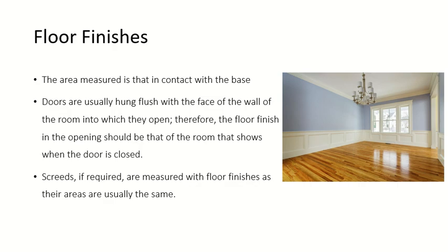I'm not talking about the area of the door. I'm talking about the area which is under the door when you open it. So there is no deduction done for that, because the door usually opens completely till the wall. So that area is usable. You open your door and you have the whole area which can be used. Screeds and floor finishes normally have the same area.